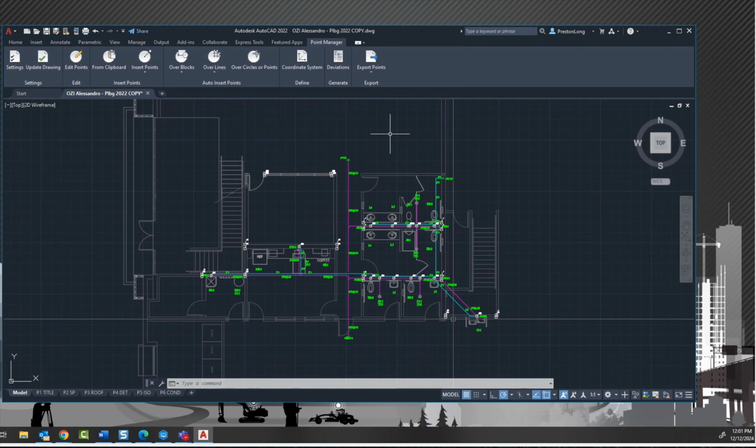A lot of the times I'll find that the structure guy is using the total station and he's got control, and he may give us his control points, and they may be 4 foot offsets off of something. I would put those same ones in my file, and then I would set up on his, or use his control too, and then we're all in the same spot. So it just depends on each job, the GC, and what you ask for at the beginning of the project. If you don't ask, they don't know.